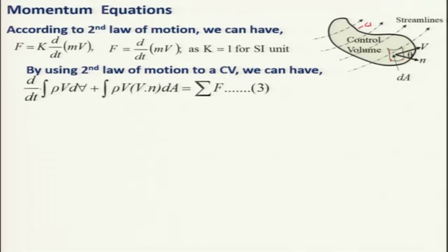And if you look at it, the rate of change of momentum in this control volume, plus the momentum flux, is equal to the summation of the forces acting on the control volume.